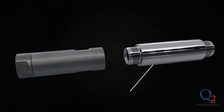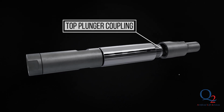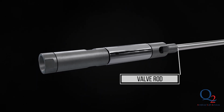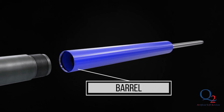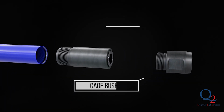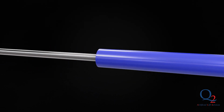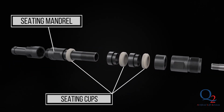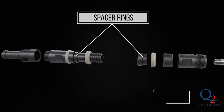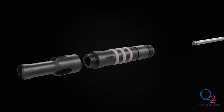Valve rod guide, we've got our barrel that goes across, and of course on the bottom you've got your standing valve and your cage bushing that screws into your barrel. And on the top, this is a top hold down. We also have a bottom hold down pump that I'm going to show you in a bit. The top hold down pumps are usually a little more shallow, and the bottom hold down pumps are run a little bit deeper into the reservoirs.